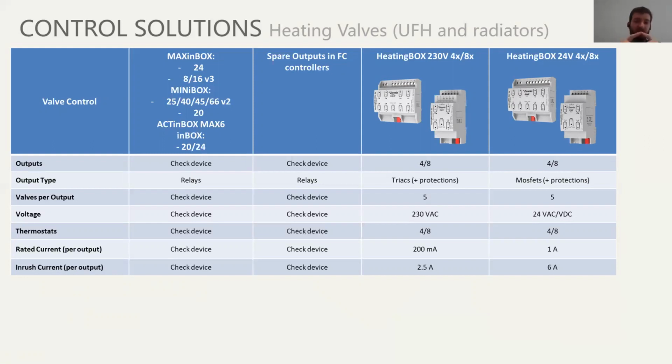So when using, for example, an underfloor heating radiator and controlling a valve with PWM, a very common PI cycle time for underfloor heating would be 15 minutes or 30 minutes. If you have that with PWM, every 15 minutes you have 2 switches because it's turning the device on and off. So with the relay, you can make the calculation: if you put that to 30 minutes, that would be 48 times a day.